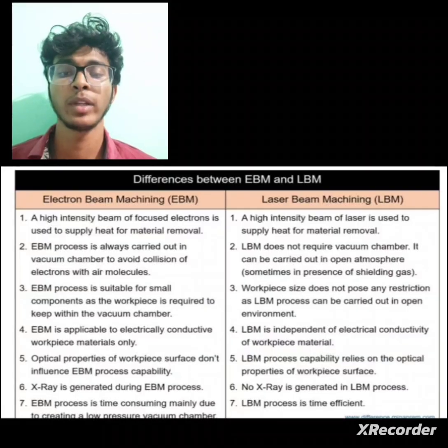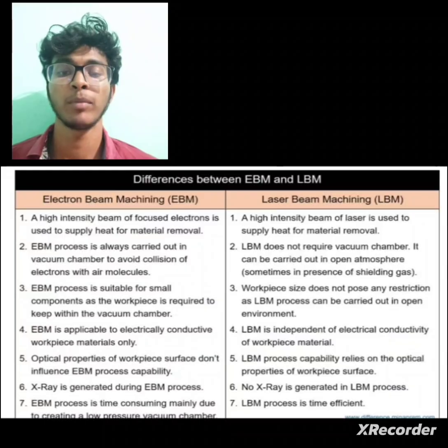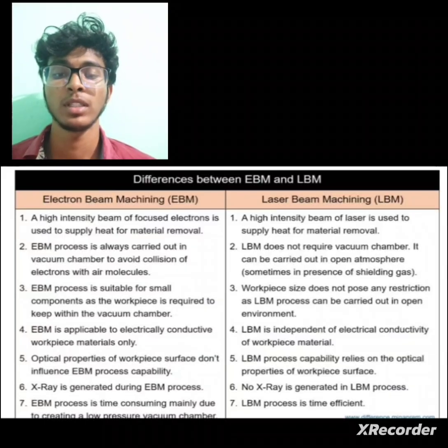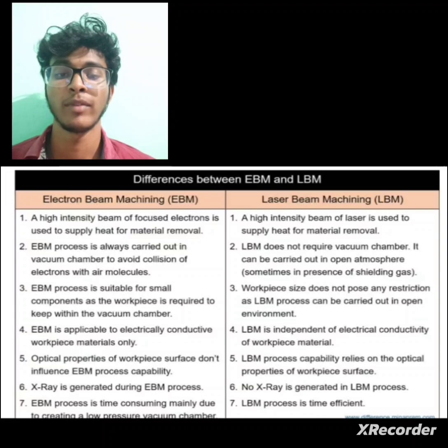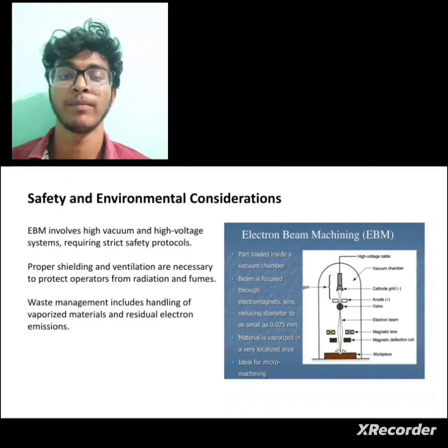X-rays are generated during EBM process. No X-rays are generated in LBM process. EBM process is time consuming mainly due to the time required to evacuate the vacuum chamber. LBM process is time efficient.